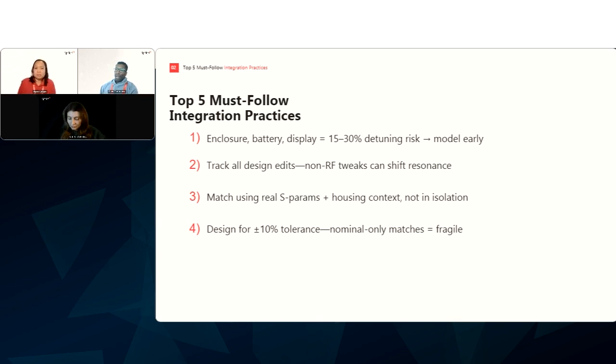Well, it all depends, right? So I would say plus or minus 10% is a good start, but it all depends on the RF bandwidth that you're working with. Now, for narrowband use, you need a tighter tolerance, because those frequencies can shift or drift quite easily, and you can be mismatched quite easily. So you want to make sure that your component tolerance, in other words your Q, is pretty high, and that way you stay within the performance requirements that you want to adhere to.